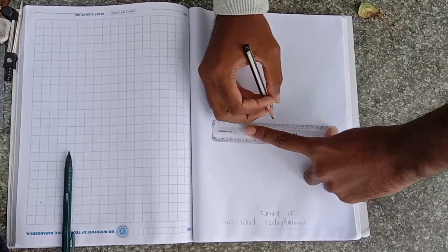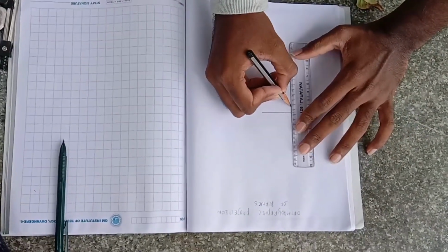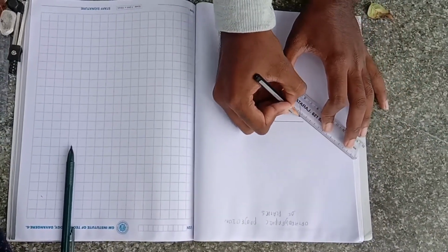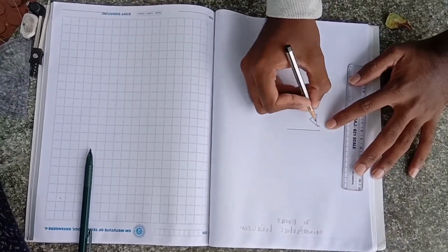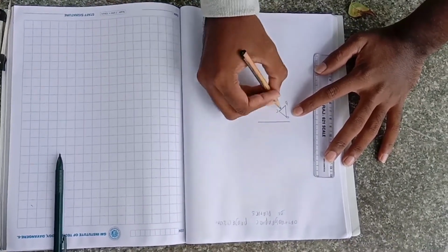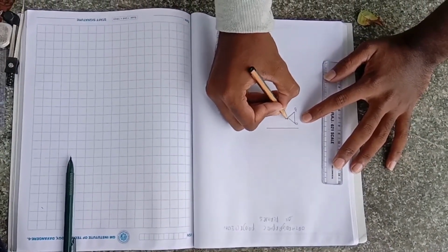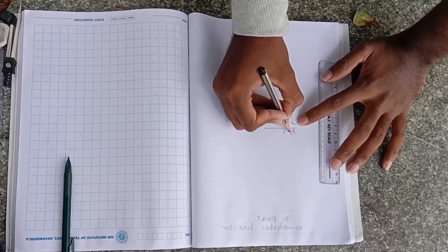If the triangular lamina lies on one of its edges on HP, it has to lie like this. Here this is the edge AB and this is the corner C. If it lies on the corner, it lies in this position C, and this is B, A dash.